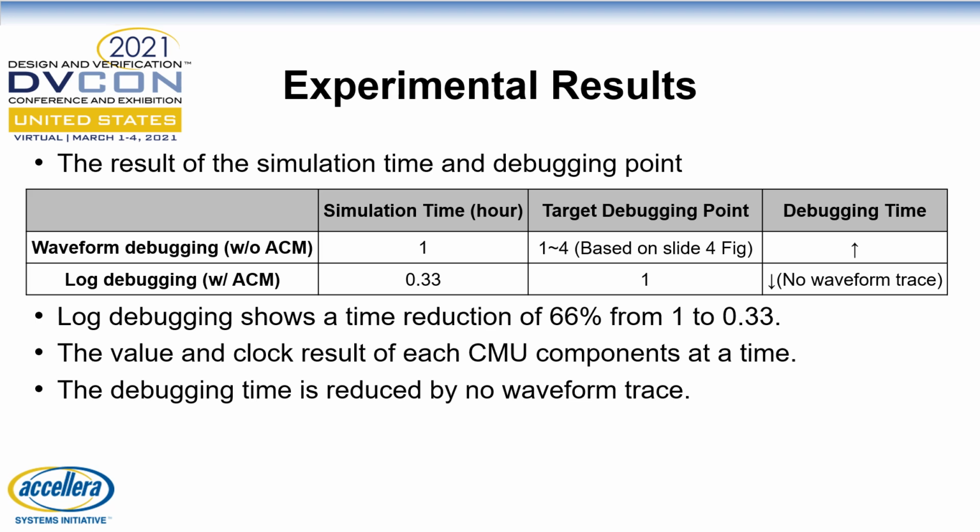In our case, the number of target IP clocks is 1748. This number will increase according to the number of DFS levels. If it has 3 levels, the total number of clock corners will be 5244. It means even if clock errors occur under 1%, 52 IP clock issues should be analyzed. The log-based debugging for the clock is useful in this case.